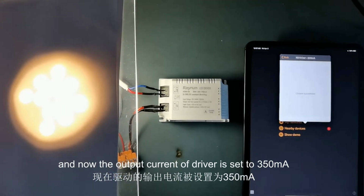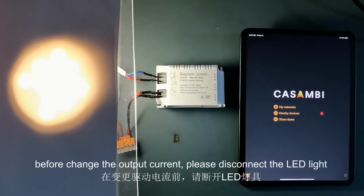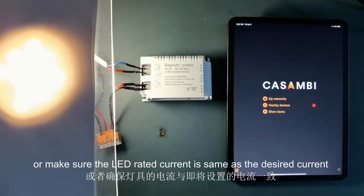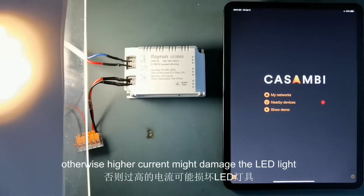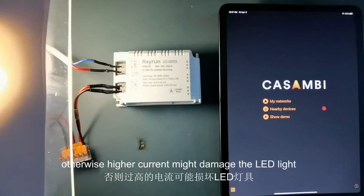350 mA. Before changing the output current, please detach the LED light, or make sure the LED light's rated current is the same as the desired output current. Otherwise, if you change to a higher output current, it might damage the LED light.